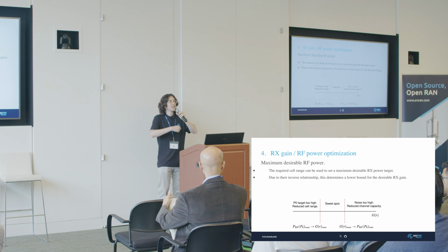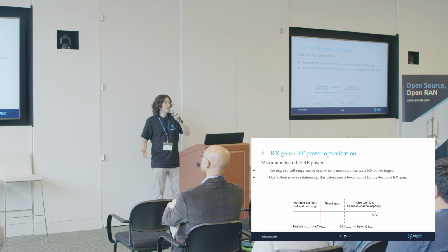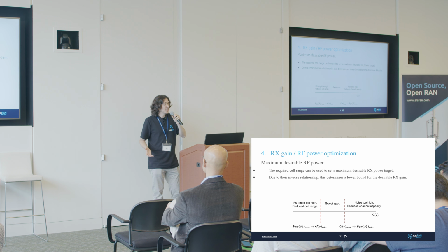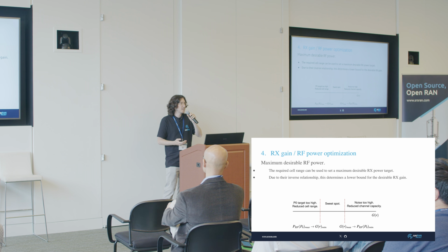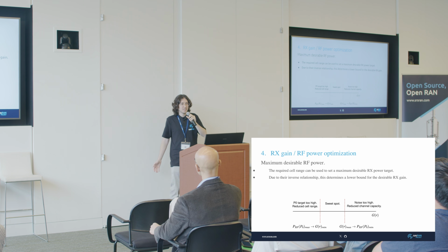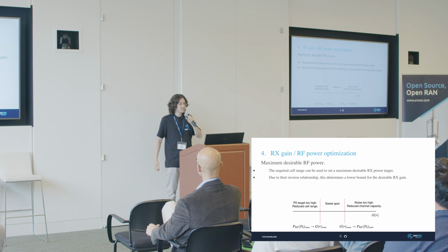Of course, the UE transmits a lot of power, so it's going to overcome all the interference, and we don't really care about anything else, so it should work really well, right? Well, yeah, but if you do that, and then you move the UE 10 meters away, suddenly you don't have a signal anymore, because the UE is going to reach its maximum transmission power very quickly. And what this means is that your cell range will be greatly reduced.